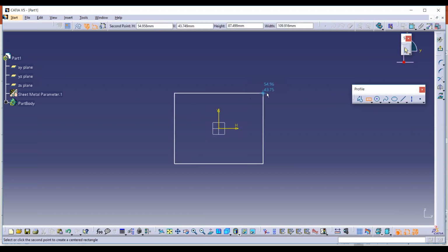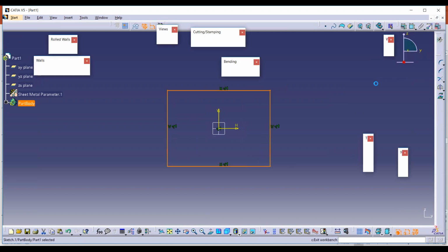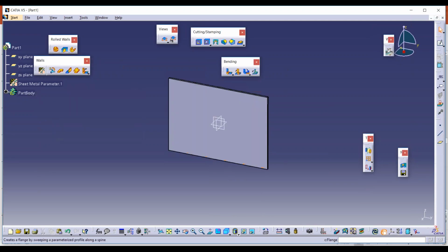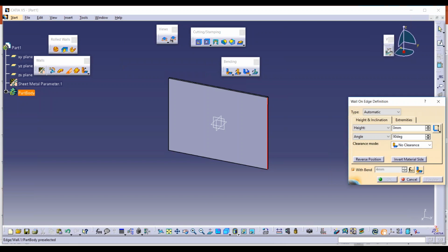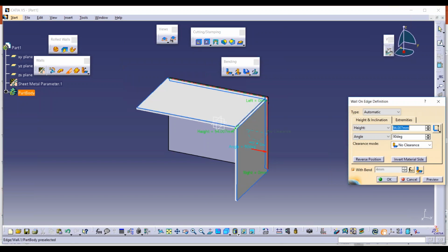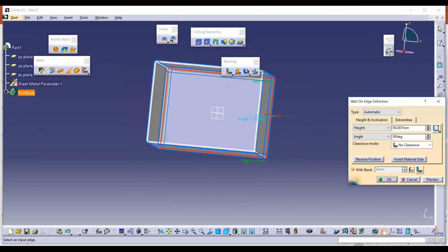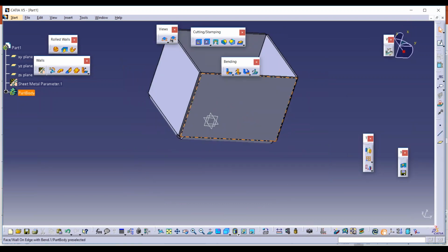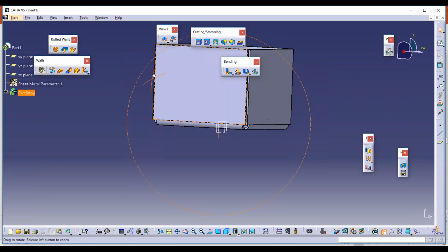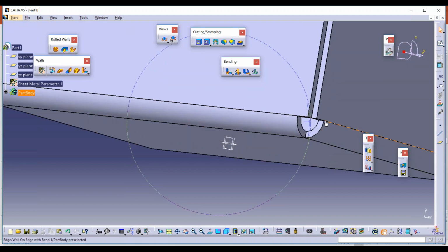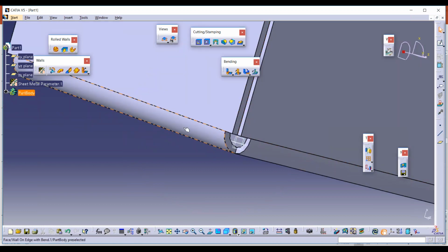So now I'm creating a primary wall. Then I'm generating secondary walls right here. So this is my secondary wall. As you can see, by default it will have some corner reliefs at the corners. Can you see? While generating itself, it will create some corner reliefs.